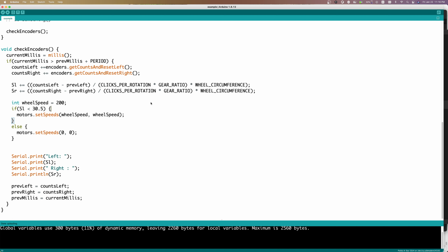And the reason for that is because you might have noticed my pretty quick standard edition here, moving at half speed, actually makes an audible thump when it gets to the end, because the back end is actually flipping up and it's moving forward a bit further than it should. Imagine getting in your car and driving at 60 miles an hour and effectively trying to stop instantly. That's not going to happen. Now, obviously our robot does not have the physical weight of a car, but it still has to deal with this problem.